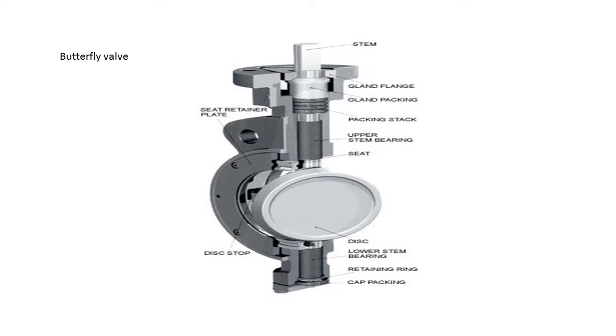When the valve is fully open, the disc is rotated 1/4 of a turn so it allows almost unrestricted passage of the fluid. This valve may also be opened partially to try to control or throttle the flow of fluid, but like a ball valve, it is not well suited for this application. The valve shown here is a flange connection valve.